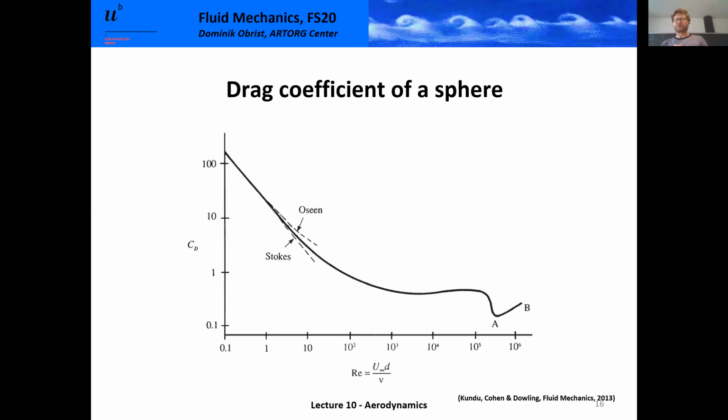And this is actually used in many situations. If we're already somewhere close to this Reynolds number, and if we manage to tip the flow a bit over the edge of this drag crisis, we can significantly reduce the drag of an object. This is, for instance, done in golf balls. If you look at a golf ball, you see all these little dimples, and you may ask what these dimples are good for. At least, that's one theory.